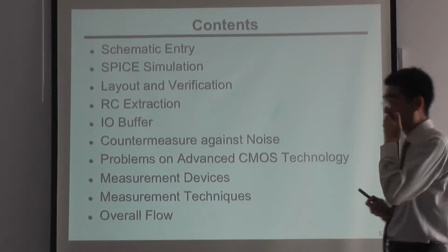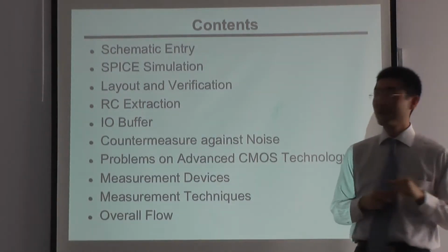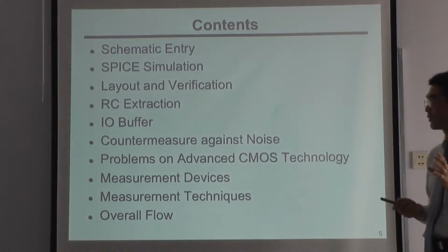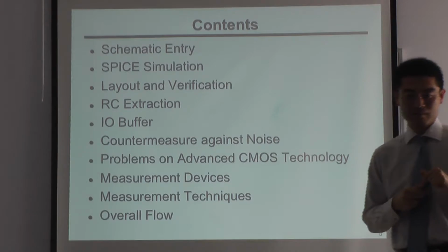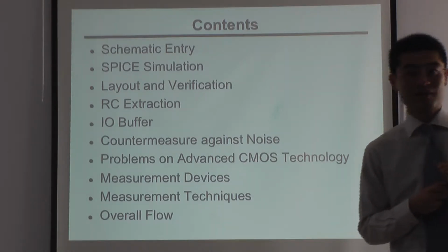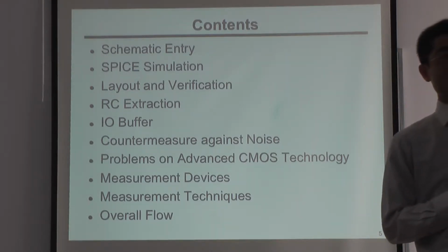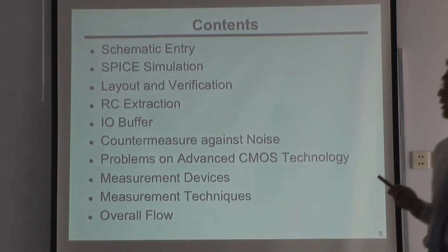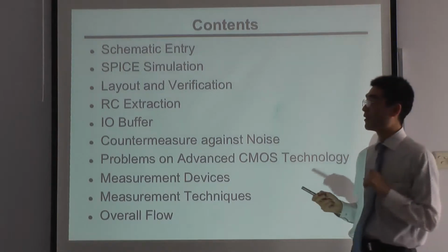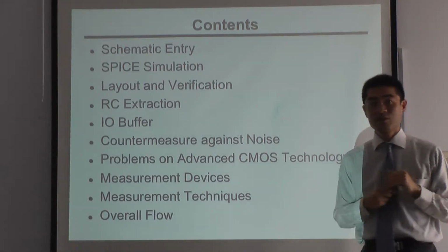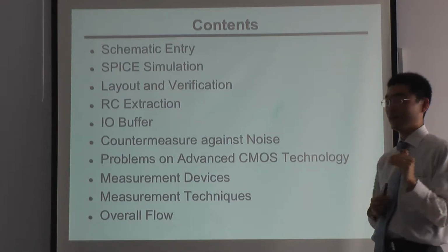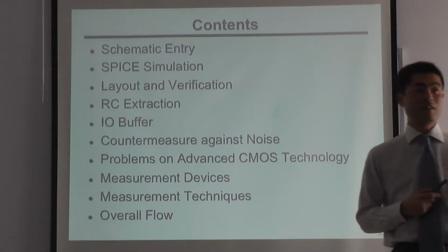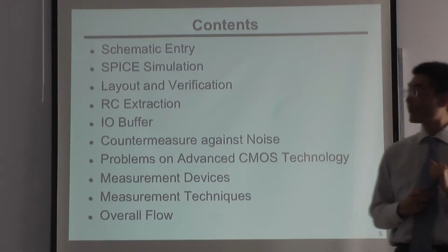So what I'm talking about is the step-by-step flow of designing a circuit. Maybe you are a circuit designer and you design a circuit. First, you have schematic entry with Cadence. And then you run SPICE simulations, and then you draw the layout. And after layout, you will run LVS and DRC as verifications.